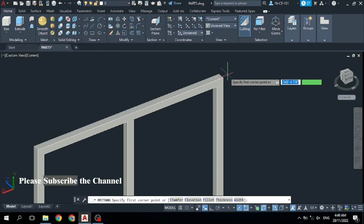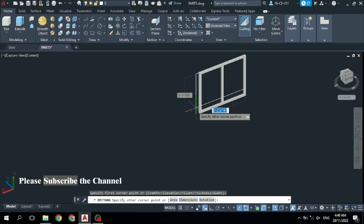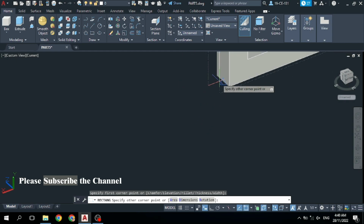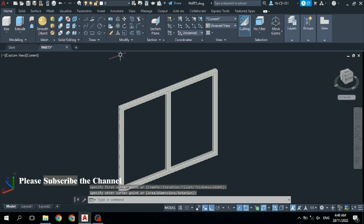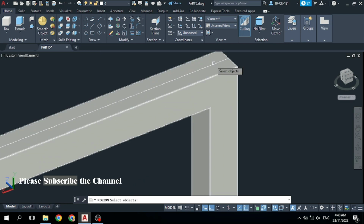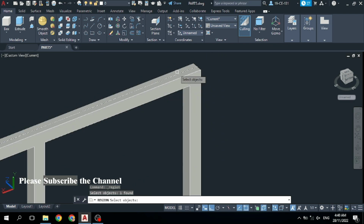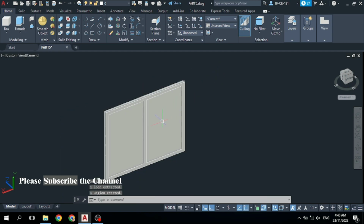You can see this rectangle and start from this middle point and come to this corner and finish here at this middle point. And then after that come to this draw and click on this region. You can see this region and select this rectangle which you have drawn. Simply select it, click on it, and then press enter or right click. Now you can see it is changed to a region.